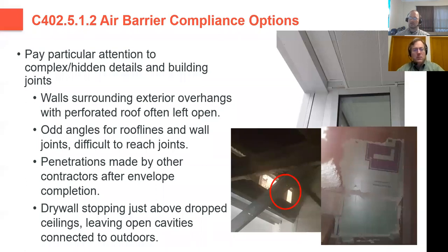And what happened was they had open plenum returns on some heat pumps in this building, and those heat pumps just couldn't keep up with that load as they were drawing in straight outside air, and they were designed to condition mostly inside air. So it's very important, if you're specifying an air barrier assembly, that your details call out any areas that are going to be difficult to reach or might have hidden pockets in them, and that those details call out specifically how those are going to be sealed and how you're going to achieve your continuous air barrier.